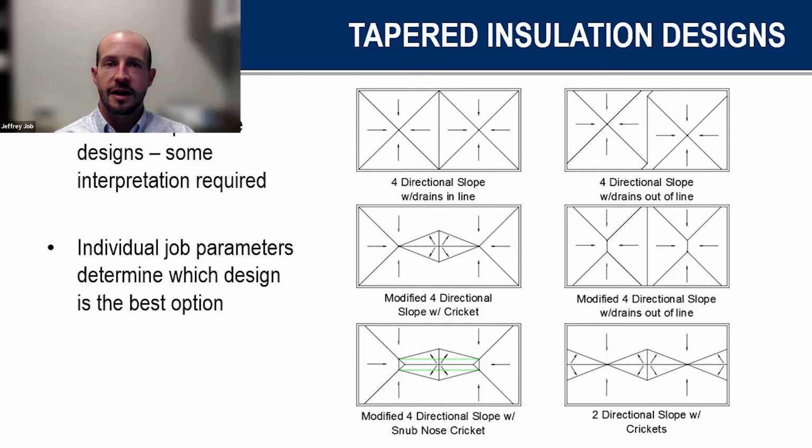requirements, things like that, even from a retrofit standpoint as well. Maybe you don't have enough slope, or there's ponding for whatever reason. Coming back and retrofitting a system with tapered when you're maybe doing a tear off and a re-roof, adding some slope to that system, supplemental slope, things like that will all be ways to achieve the required slope requirements for that project, and can be done in a lot of different fashions.